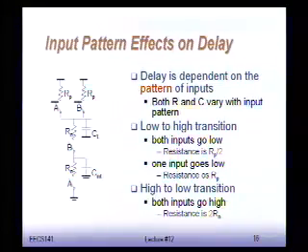But it's very hard to do better than this, actually, unless you know that that particular input pattern is never going to be exercised, which you typically don't know. Then you always need to take into account the possibility that this is going to happen. So in the end, we're only interested in the critical path, really, in the worst case input pattern. So for this particular gate, the worst case low to high is when only one of A and B goes low.